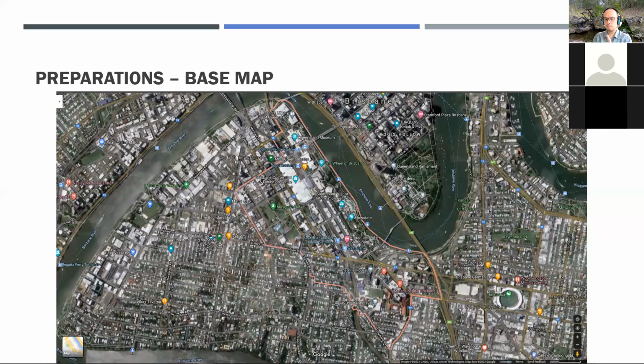A land use planning project for a relatively large area, for example, several hundred acres, could conceivably have a relatively small scale base map, 1 to 200 or 1 to 400. On the other hand, a site planning project for a residential or commercial building on a much smaller scale, 1 acre or 1 hectare, could have a relatively large scale base map of 1 to 20 or 1 to 40.